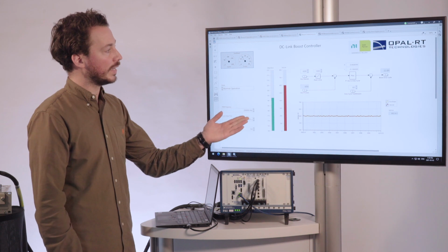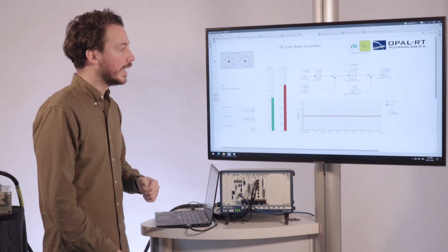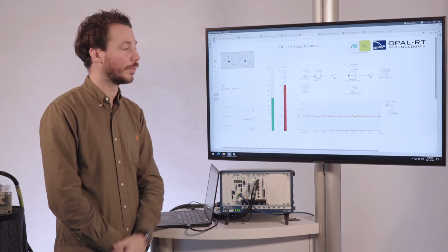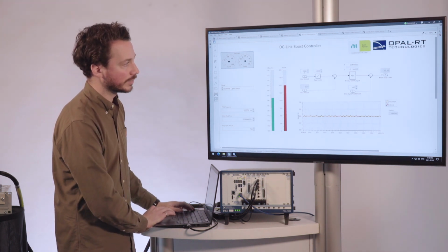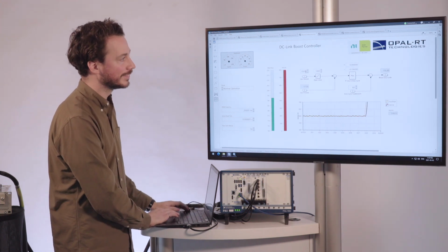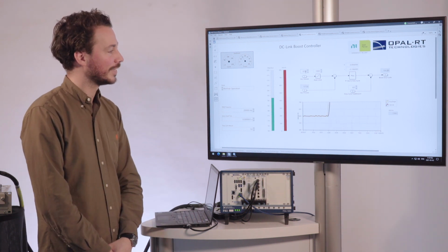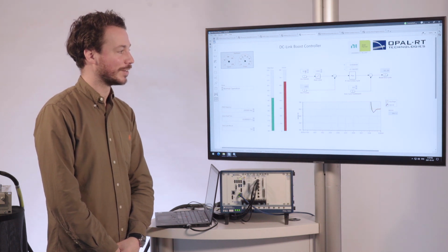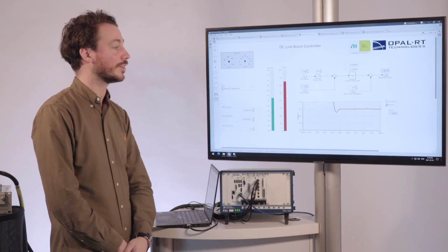What we can see here is we have a desired voltage output of about 600 volts, and we have a simple PI controller that's going to regulate the voltage to make sure we stay within that 600 range. Of course, if I wanted to, I could change this, for example, from 600 to 650, and we'll see that, oh, that's a little bit high, sorry. Let's put it back to 650, not 6,000. It might take a little bit of time to go down, but eventually we come back. So the boost is now regulating the voltage at 650 volts.